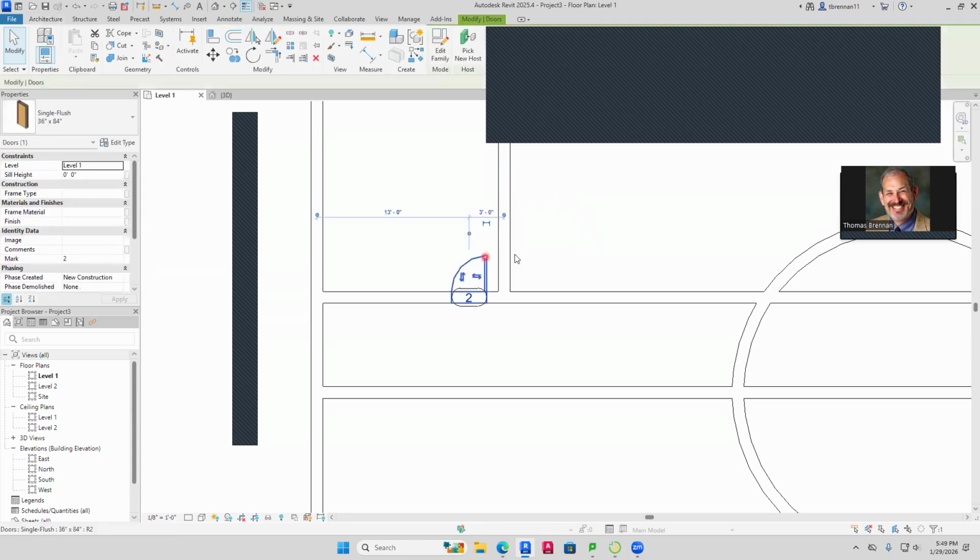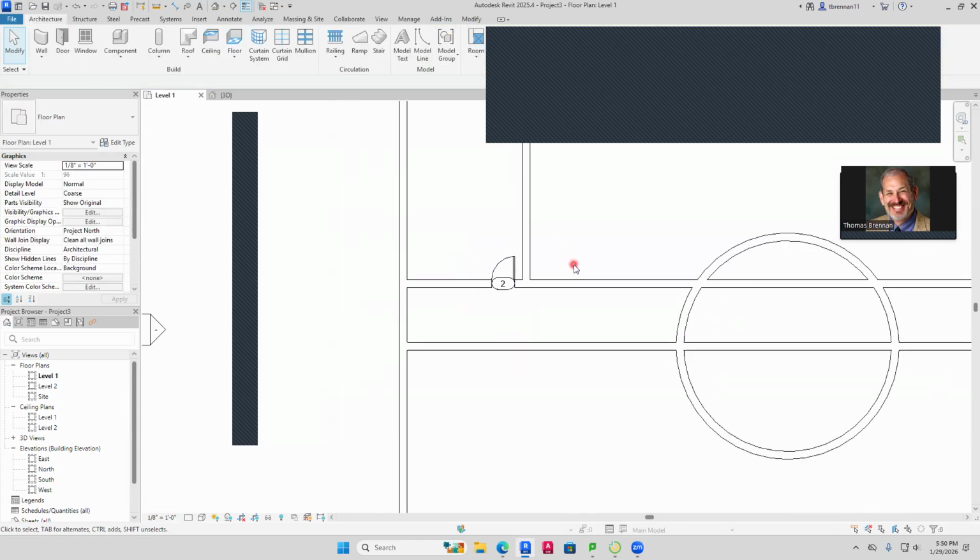And then if you click on this, you're going to notice you have 2 sets of arrows. One set goes up and down, one set goes left and right. Just go ahead and click the up and down arrow and notice what it does. It flips it in different directions, okay? Revit's full of these kind of things. So you just want to look at these little things because they can actually show you a lot of ways to update your design and save you a lot of hassle. So did you guys see how that worked? It flips around. Press your escape key.